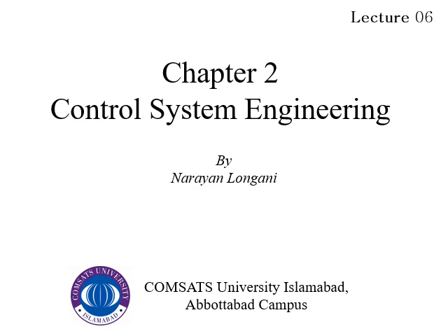Then we studied degree of freedom. For degree of freedom, we have to find how many test points or points of motion exist in a system. A point of motion in a system is defined as a point which can move freely while all other points of motion are held stationary. And the number of these test points will be equal to the degree of freedom, and also define the number of equations required to define the dynamics of a system.